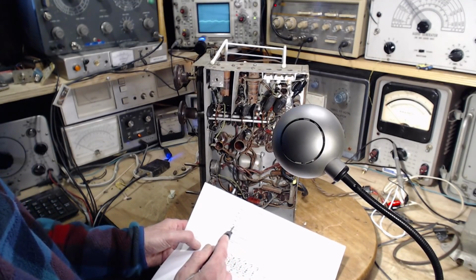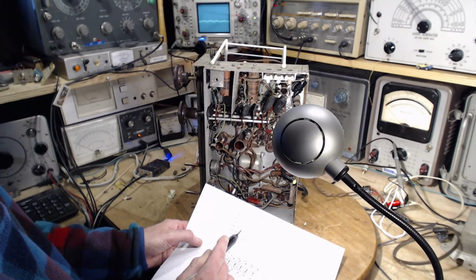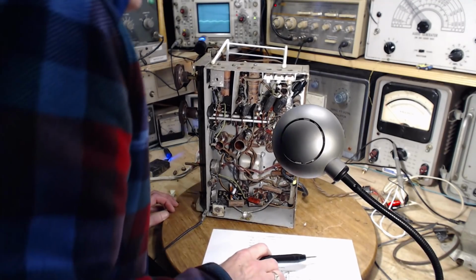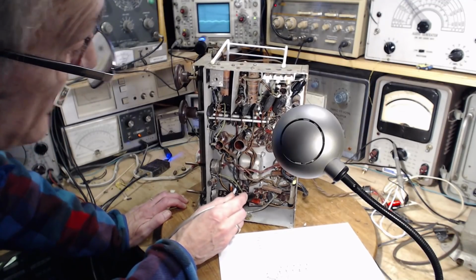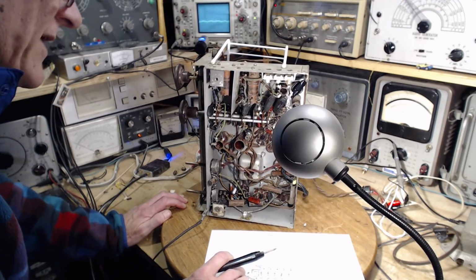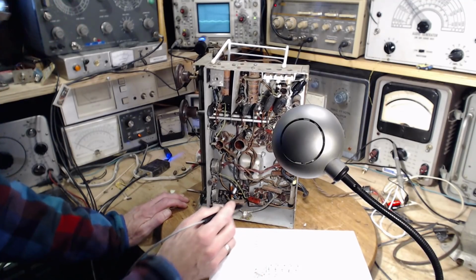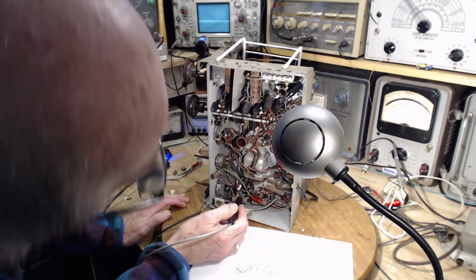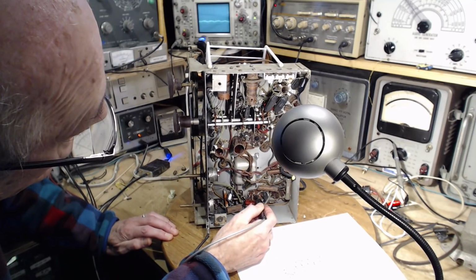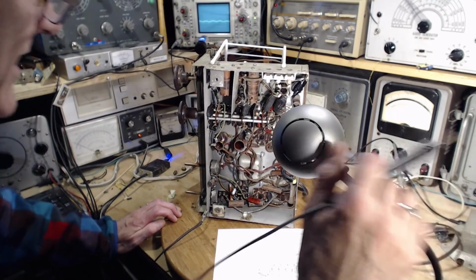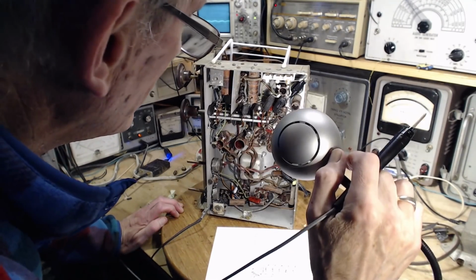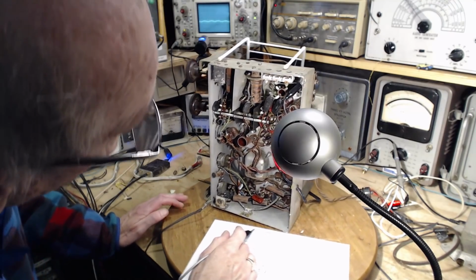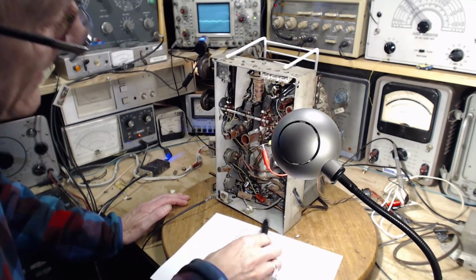Okay, that's good. Now we're into the audio tube. So the 6SQ7, which should have 195 volts on pin number 6. And the 6SQ7 is this guy right here. We want to find on pin 6, 195 volts. So I'm counting here. Where's the little nubbin? There's the key. 8, 7, 6. Oh boy.